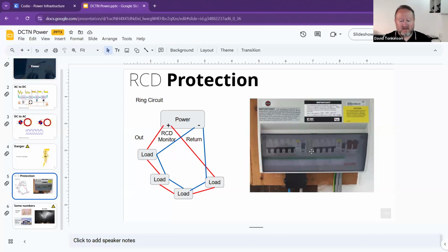As well as this and this. Okay, so those are basically RCDs on the system. And that RCD will shut off all of these fuses. It won't flick them all, but it will basically kill all the electricity to all those fuses. So if there's a fault in any one of those circuits, the RCD pops and you lose the lot.